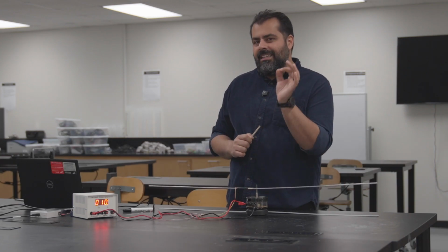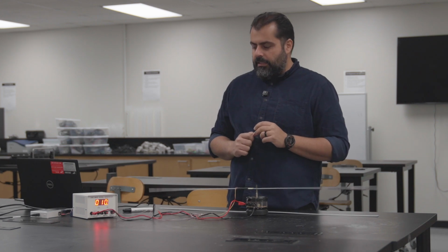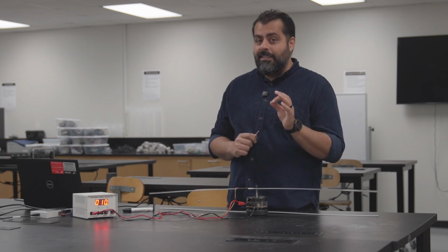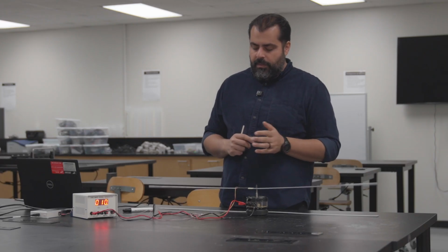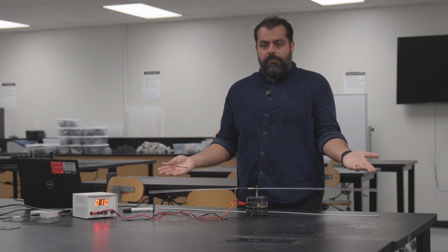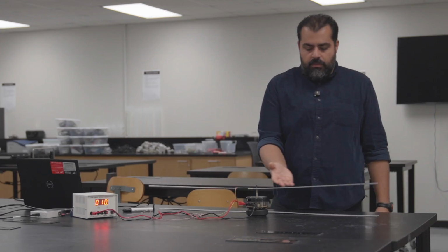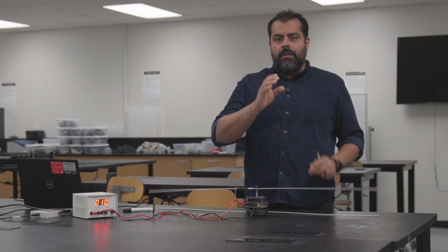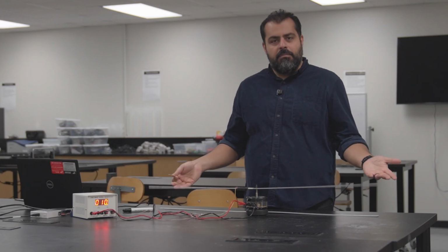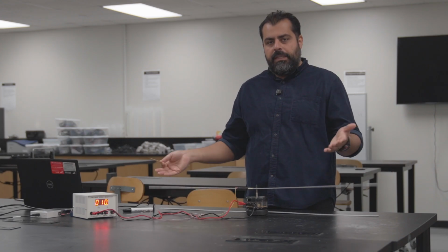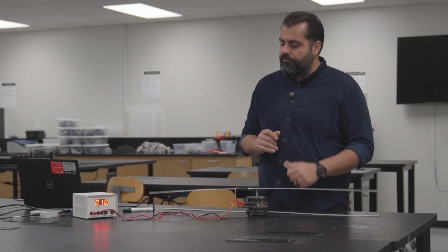For the first cantilever beam vibration, though, this is a trick question, because for the first mode of vibration there are no nodes. There is no point on this beam with zero lateral displacement, which is something we can obviously see, right? So this closely resembles the cantilever beam theory, right?